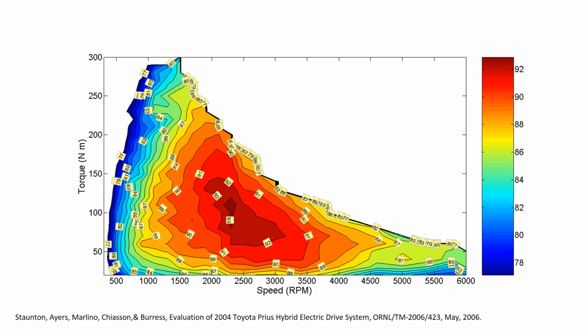In this figure, we see the same torque versus RPM diagram plotted for a real brushless DC motor used in an automotive drivetrain. In addition, a heat map showing the energy conversion efficiency of the electric machine assembly for different torque and RPM values is plotted on the same axes. Note that efficiency is high over the entire range, but noticeably lower for extremely low and high RPM values. When we model electric machines using QSS and MATLAB Simulink, a map like the one pictured here ultimately governs the response of the model and helps us make intelligent choices about vehicle designs.